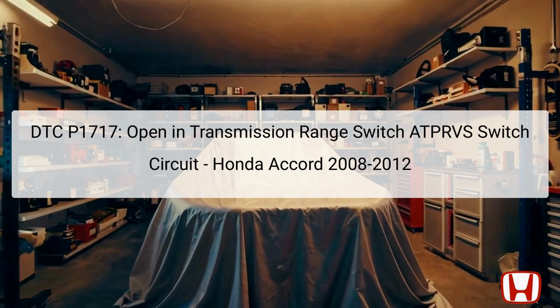Welcome to the diagnostic presentation on DTC P1717 for the 2008 to 2012 Honda Accord. This code signifies an issue with the electrical circuit related to the Transmission Range Switch ATPRVS, indicating an open circuit condition. The error cannot arise from mechanical problems in the transmission system, but is purely electrical in nature. The transmission range switch is crucial for relaying the position of the shift lever to the powertrain control module, PCM, aiding in the functioning of the automatic transmission system.